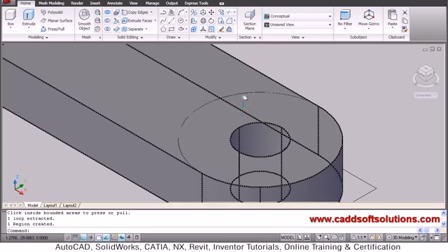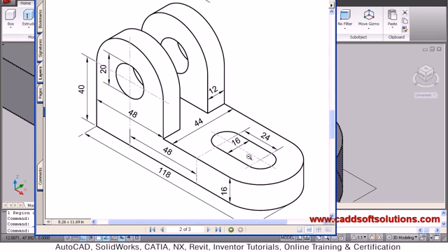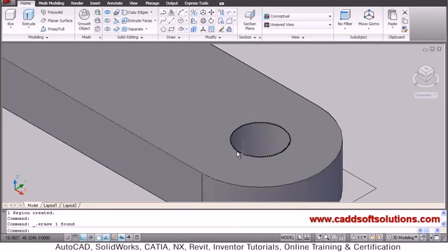Then after that, I don't want this circle, so I will just delete this circle. Then from here, this portion is there. So it is 24 and again that circle is there. So I will just create a line of 24 length from the quadrant of this, of length 24.